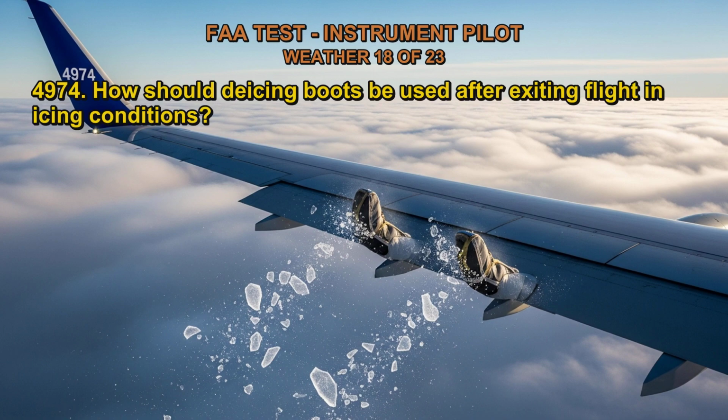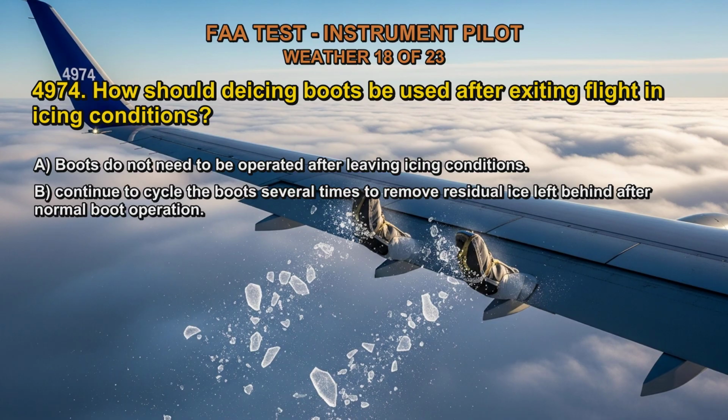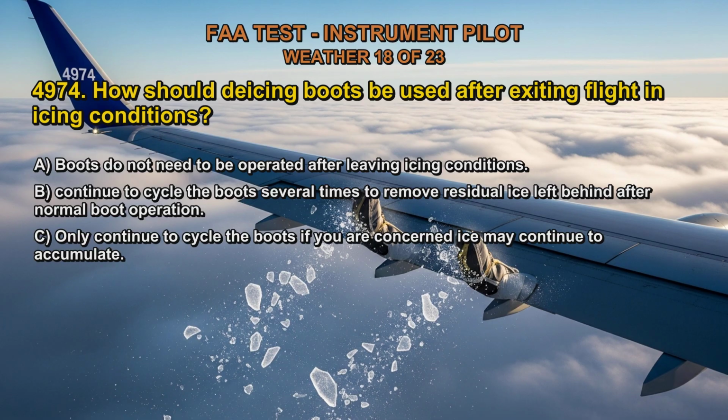4974. How should de-icing boots be used after exiting flight in icing conditions? A. Boots do not need to be operated after leaving icing conditions. B. Continue to cycle the boots several times to remove residual ice left behind after normal boot operation. C. Only continue to cycle the boots if you are concerned ice may continue to accumulate.